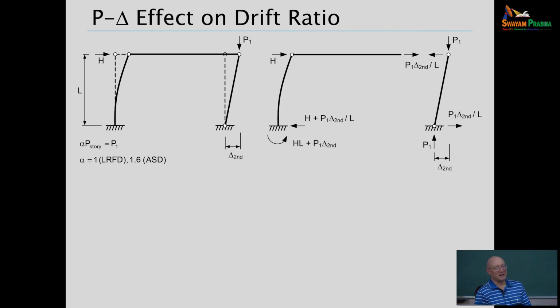Okay, so the engineers that prefer ASD want to see dead plus live. That's our load combination, dead plus live. I'm designing some rigging for something. I want to be able to do dead plus live. All right, so we have dead plus live now. They've sorted out, by reliability basis, what the other ASD factors should be. Problem solved, but it's been a 2.5 year mess. And if we just had LRFD and not ASD, we wouldn't have been losing all that time.